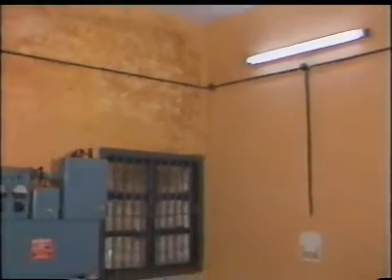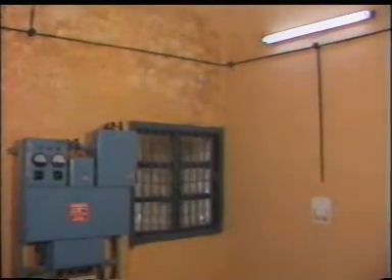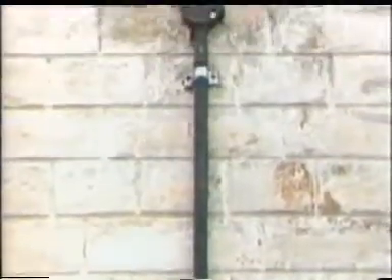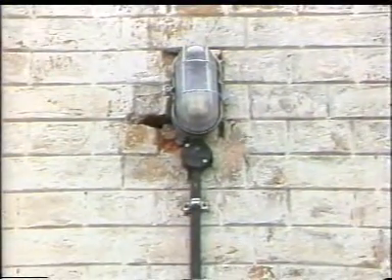Presently, the most commonly used wiring method is the conduit wiring, where the PVC cable runs through the conduits. In surface conduit type of wiring, steel or PVC conduits are fixed to the walls and ceilings with the help of saddles and staples. Whereas, in the concealed conduit wiring, the conduit is embedded in the wall before finishing.